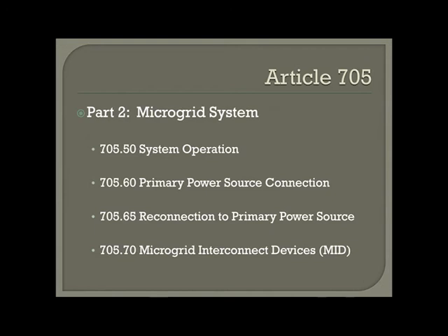And then a good time is to think about how big is your KW system? How many amps is it? And how many volts? On a 1 and 2 family dwelling, 600 volts is your maximum system you can put on it. You'd be really surprised how many electricians I ask weekly, how many volts do you think is coming out of that DC system? Most of them will say, I don't know, 12, 24. And when I tell them the average 380 to 480 volts, they're dumbfounded. Because I just use, you know, different situations, but what's your car battery? Does that thing sparkle out when you short it out? Of course it does. So think about what you're doing.